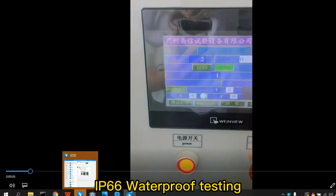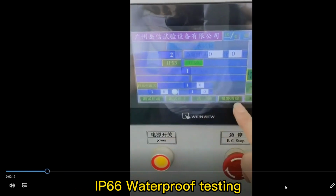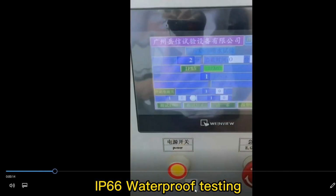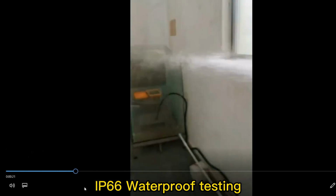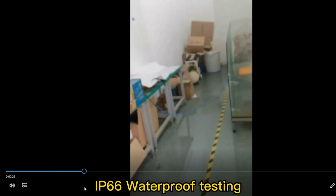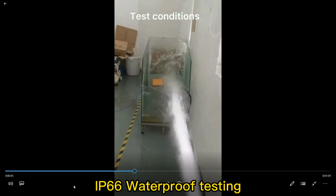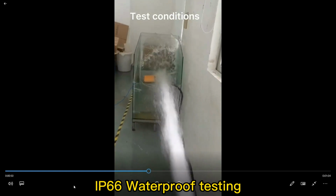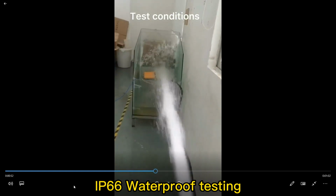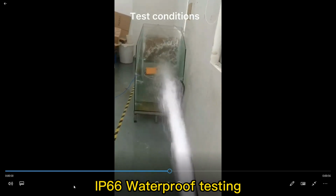The following is the waterproof test process of IP66. First, we put the phone on the test cylinder fixing table, and then we fix the nozzle. We will adjust the nozzle with an inner diameter of 12.5 millimeters, and the distance between the nozzle and the sample shell is 3 meters. Select the waterproof grade of the sample and set the water flow to 100 plus or minus 5 liters per minute. Click to start the test.